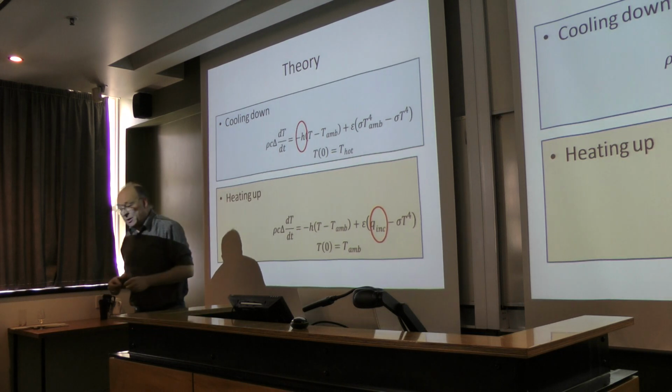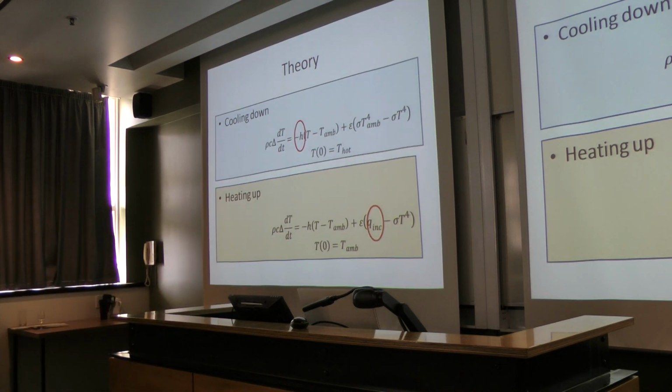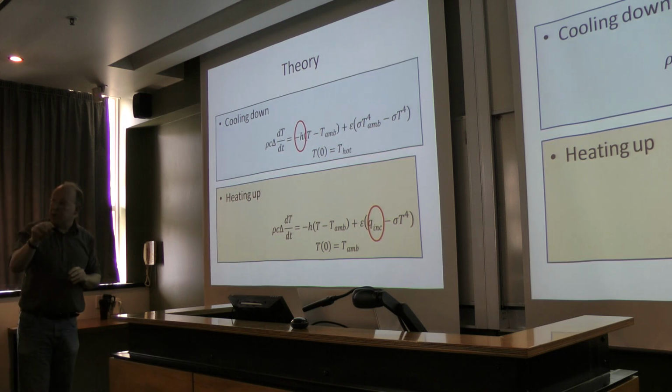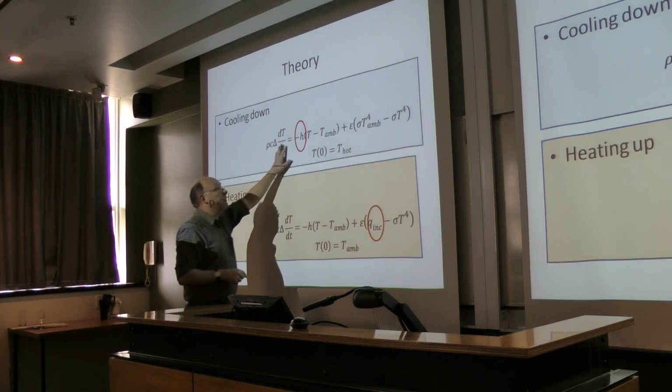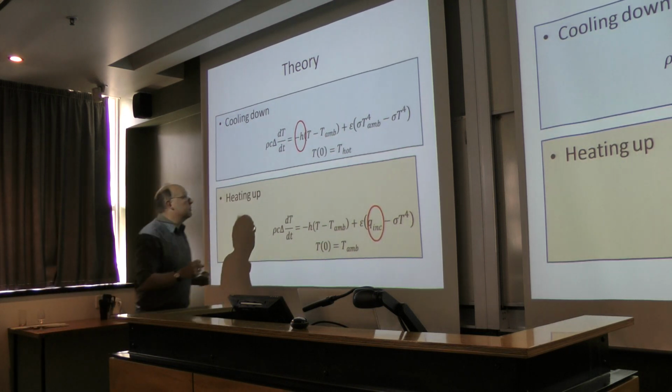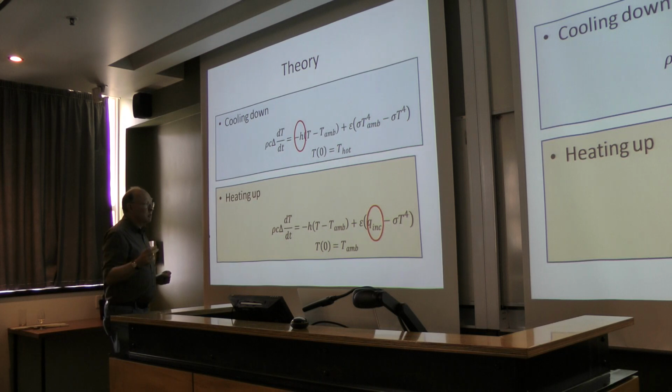So what I can do is adjust my heat transfer coefficient so that my model can predict the experimental data. When it does, that's the heat transfer coefficient. We can certainly talk about the validity of this afterwards if you really want to. Happy to do that, but I'm not going to do that now.